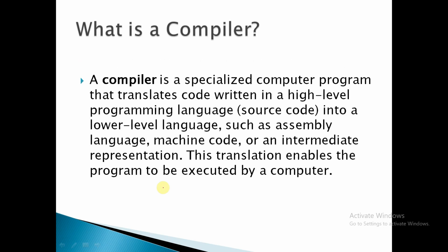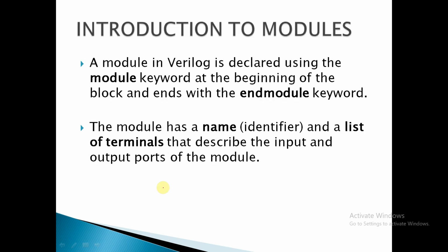So let us start with modules. A module in Verilog is declared using the keyword module. So module is a keyword, and we are going to declare it at the beginning of the block, and we are going to use endmodule. So module as well as endmodule are keywords. Any design you want to write, you are going to start your design with the keyword module, followed by endmodule. So these two are our keywords.